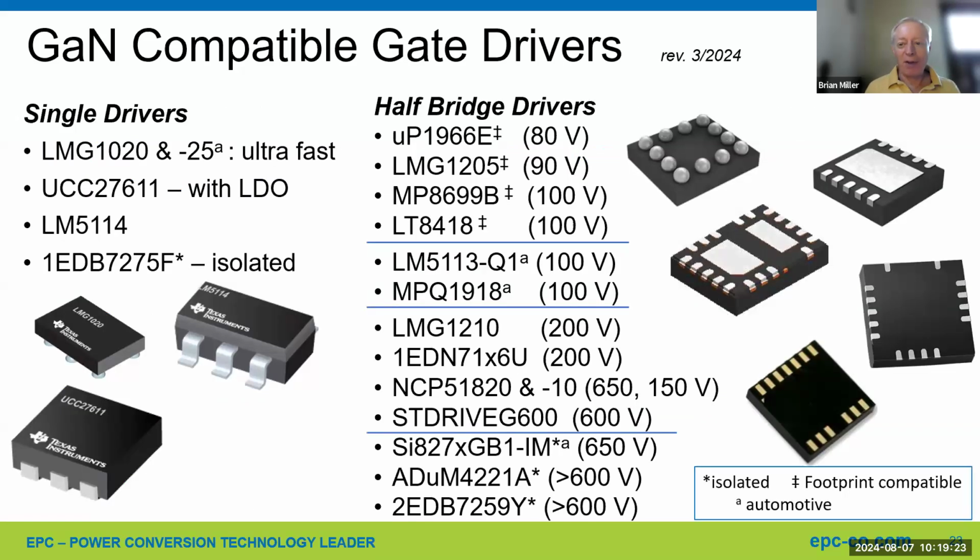So there are quite a few gate drivers made for GaN. It's really quite a list. To go over some of them, there are single drivers. There are some ultra fast ones, which are useful for a lot of applications, and they're also ultra small too. Some with or without LDOs, and some that are isolated. There are a lot of half bridge drivers. The first four are all in the same common footprint, which is kind of convenient.